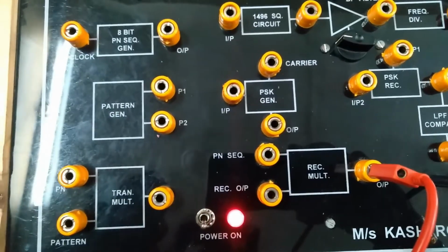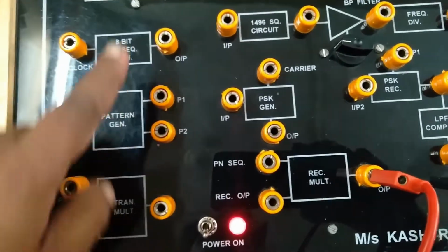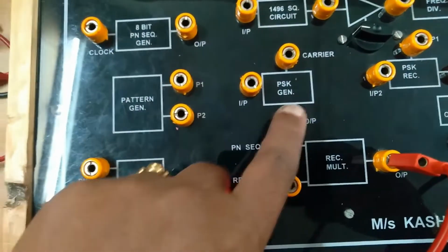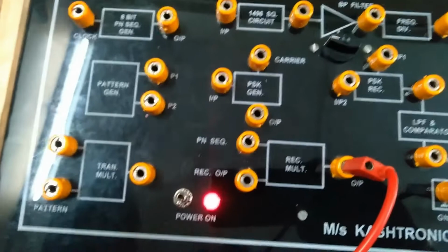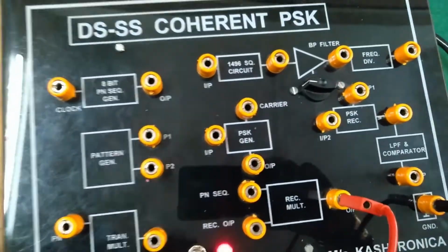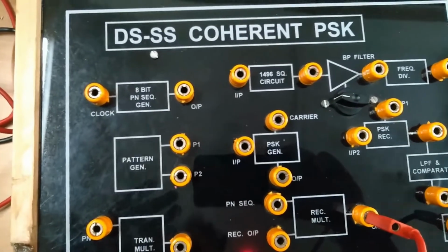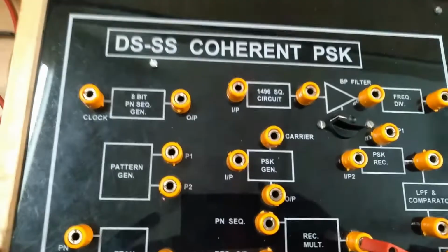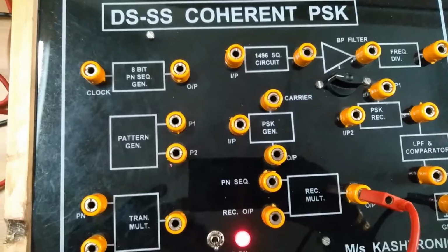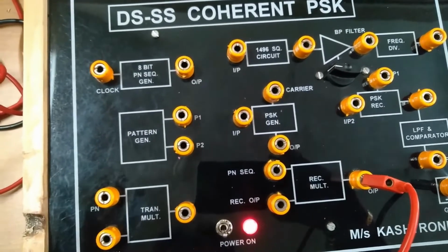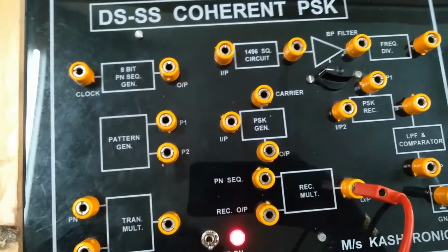So your spectrum gets increased. With only 1k, the spectrum extended up to 21k. But when I consider the PN sequence and the bit pattern, the spectrum increased to 23k. Increased spectrum means bandwidth increases. This is a disadvantage in a communication system, because if you increase the bandwidth, the number of users is going to reduce, correct? But the advantage with DSSS PSK, that is spread spectrum, is that security in the data is maintained by using spread spectrum technology. Though the spectrum utilized is more, security is going to be there in the data transmitted.